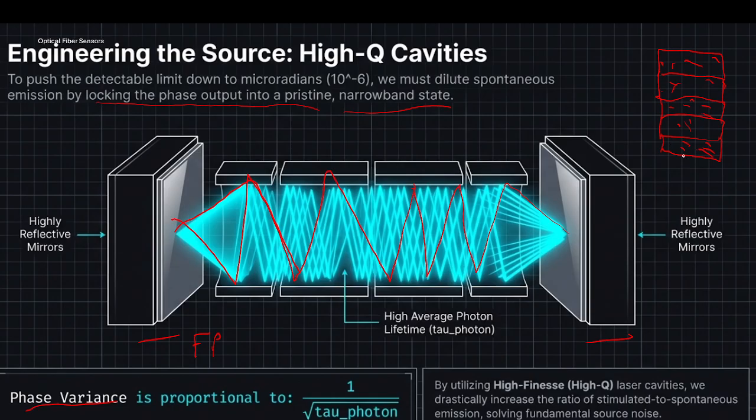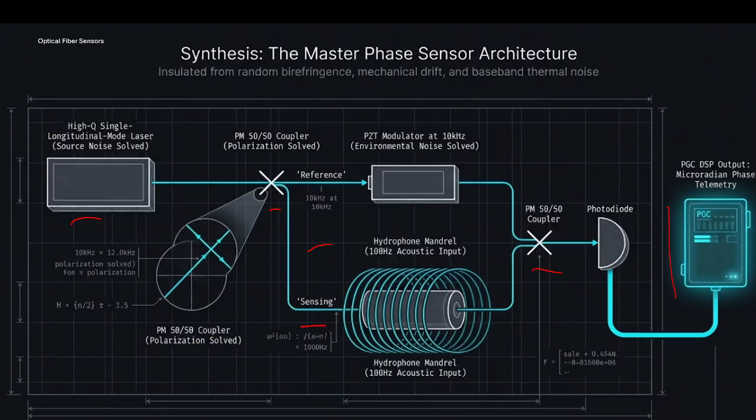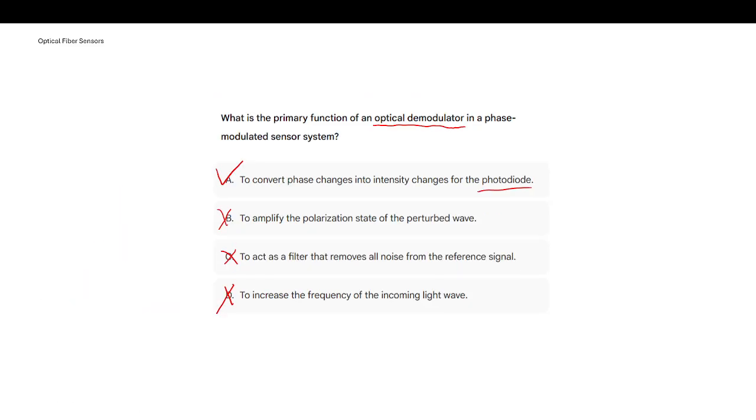Once the light is generated, the cavity captures the light and traps it inside. Suppose this is high, it will trap it inside this, then slowly send it to another one, and so on. The Fabry-Perot itself is a good lasing cavity, but the other is very costly and making it is very difficult. That's why people usually use the Fabry-Perot cavity.